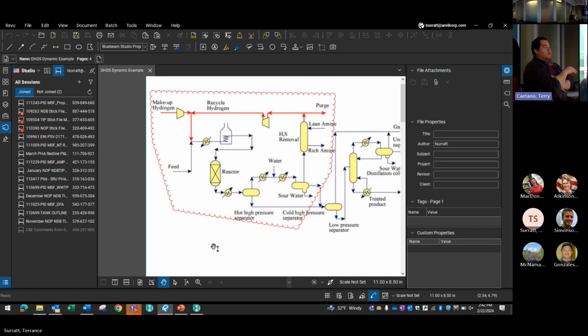You have your liquid feed and vapor feed from your compressor, and that's your highest pressure in the system. And then your pressure drops as you go through your heat exchangers, reactor, and your separators, finally ending at your scrubber at the end of it, which is typically the lowest pressure in the system, and then the lowest design pressure in the system.